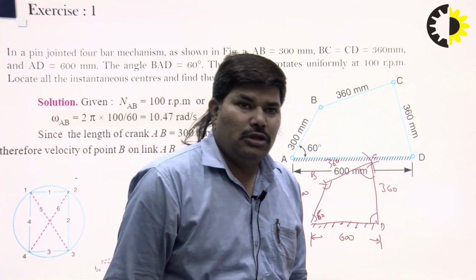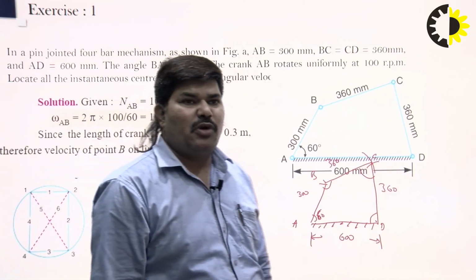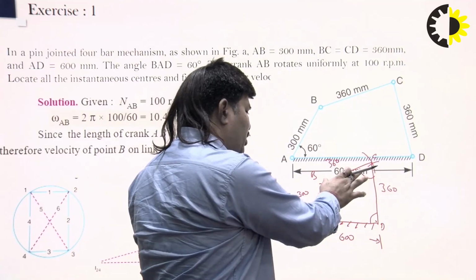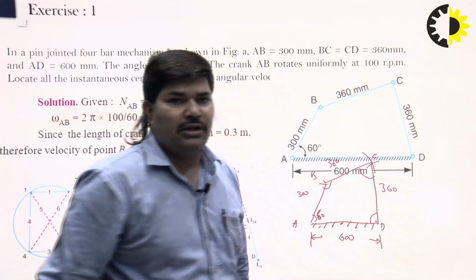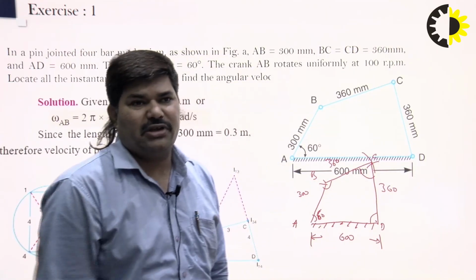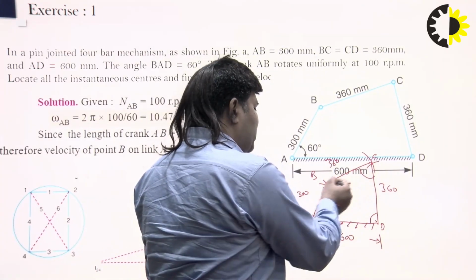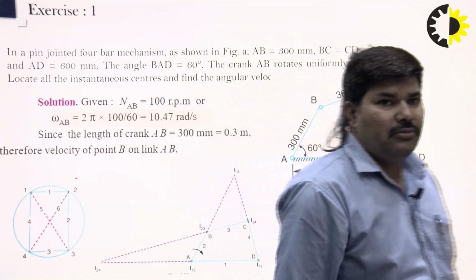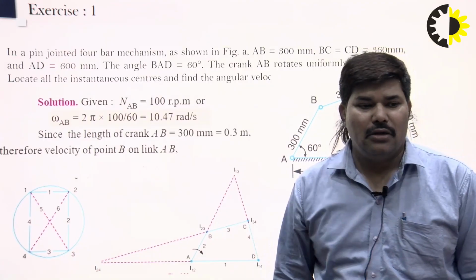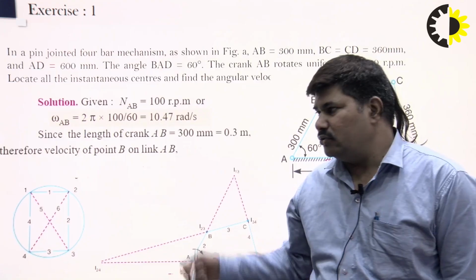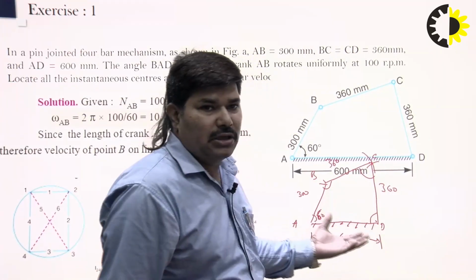ADC. So, if you mark with the protractor, you can mark here the length at point D and at point B, and at point D you can again mark. This point is cut at some point. This point you can say is C, and this point matches with the point B, and draw the line from C to D. So, you have drawn accurately B to C and D to C, right. So, we have drawn this 4-bar mechanism.